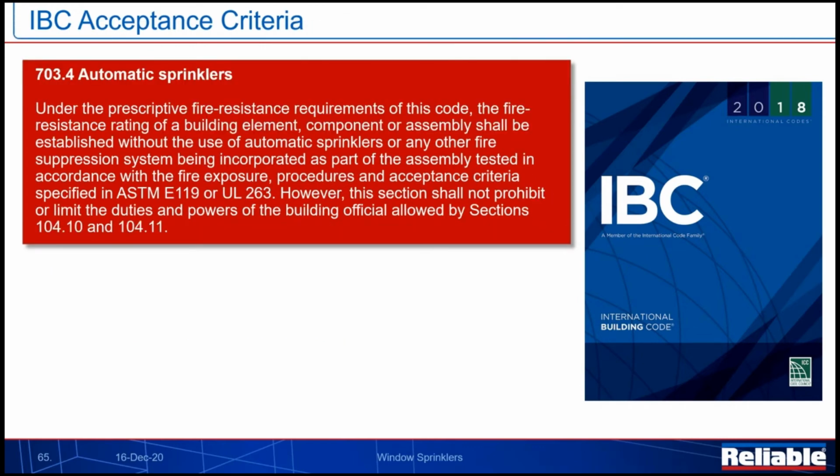And when you look in Chapter 7, there's actually a reference to automatic sprinklers. And this was added in recent years to sort of, I think, discourage the use of the products we just talked about. It really doesn't spell out their use very easily, because it says under the prescriptive fire resistant requirements of this code, the fire resistant rating of a building element, component, or assembly shall be established without the use of automatic sprinklers. Right, so it's right there saying, hey, you know what? The window sprinklers that exist, building code doesn't necessarily want them, right?